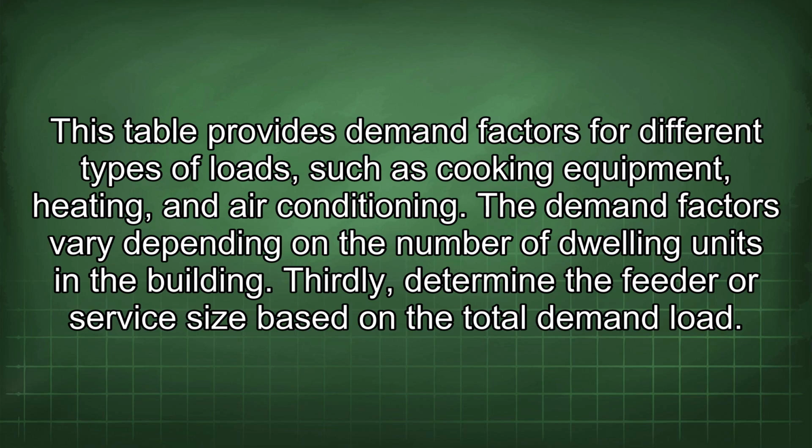This table provides demand factors for different types of loads, such as cooking equipment, heating, and air conditioning. The demand factors vary depending on the number of dwelling units in the building. Thirdly, determine the feeder or service size based on the total demand load.